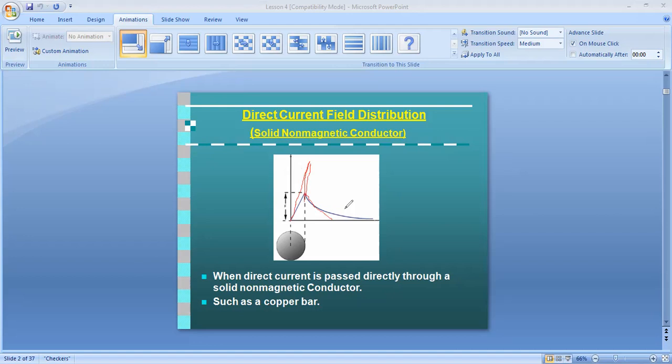Here we are not using this conductor to detect cracks in the conductor. So what is the use of the conductor? To generate a magnetic field around the conductor, and that magnetic field will be induced into the hollow jobs. This technique is known as central conductor. We can't say a magnetic conductor is good or a non-magnetic conductor is good, but we can say a non-magnetic conductor is good because the conductivity is high, so current will easily transfer in the conductor.